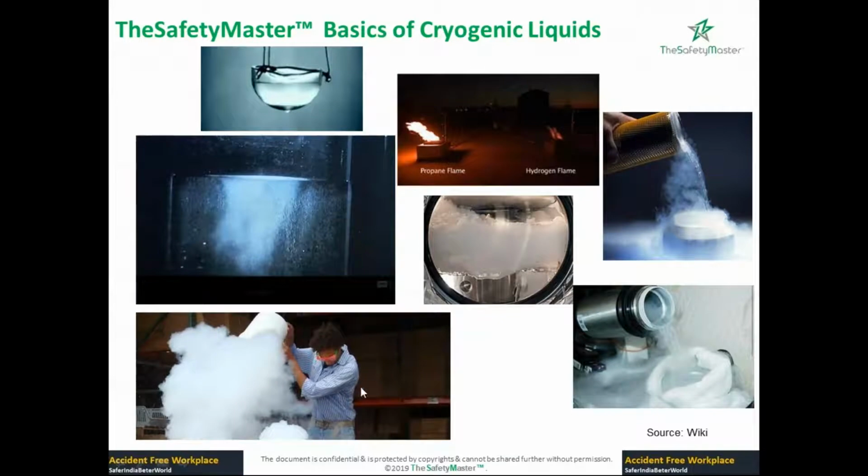And here we see this gentleman pouring some liquid, which gives off a lot of vapors. This is liquid nitrogen, so handling is the issue. He isn't wearing gloves, but many laboratories and industries do use it this way. He's using a flask to transfer liquid nitrogen. The vapors displace oxygen, so there is an oxygen deficiency hazard when handling nitrogen, which I'll come to later.